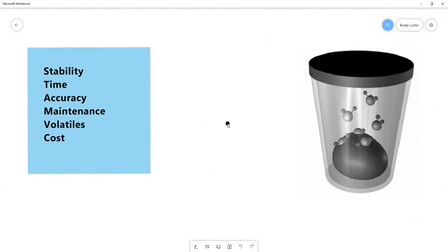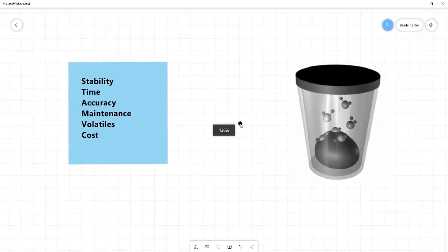The thing that's common among all water activity measurement methods is that a sample is placed inside of a sealed chamber, and then water escapes out of that sample. And over time, the headspace will come to equilibrium with the same water vapor pressure as in the sample, so that the relative humidity measured in this chamber, called the equilibrium relative humidity, will be the same as the water activity of the sample. And the methods differ on how they actually measure that vapor pressure or that relative humidity.